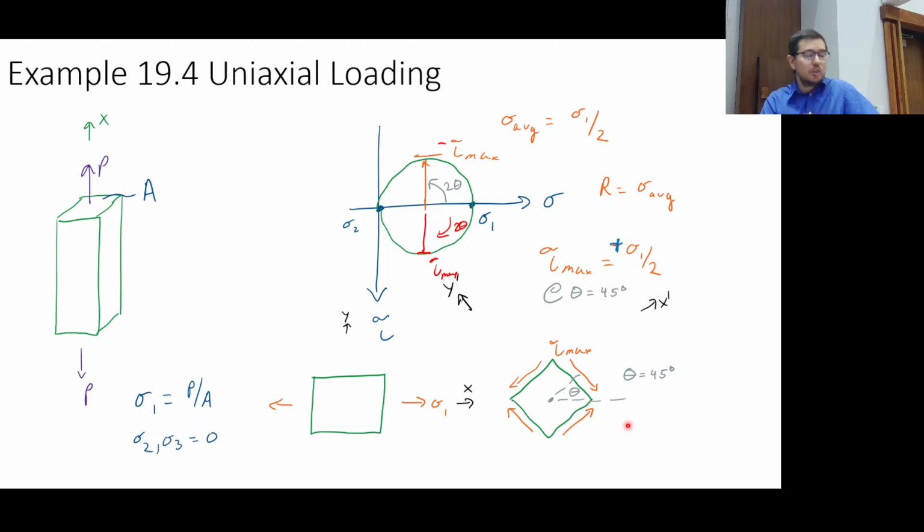Okay, so we have described now the state of maximum in-plane shear stress. And this is important. Oh, sorry. We're almost done describing the state of maximum in-plane shear stress. There are also normal stresses, right? These values are going to give us the state of stress, sigma, either this is the sigma x or this is the sigma y. They're the same, it's just sigma average. And they're coming out of the faces like this, right? Because it's not over here.